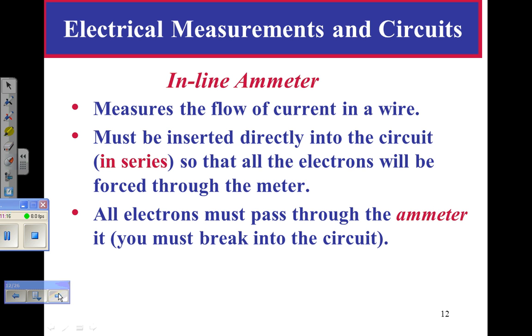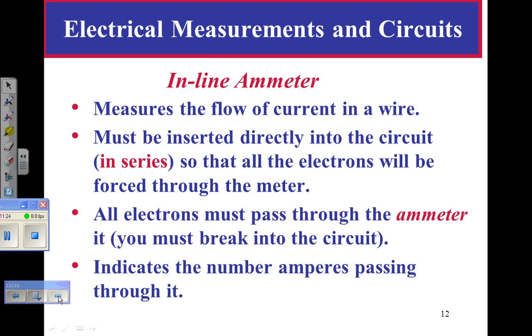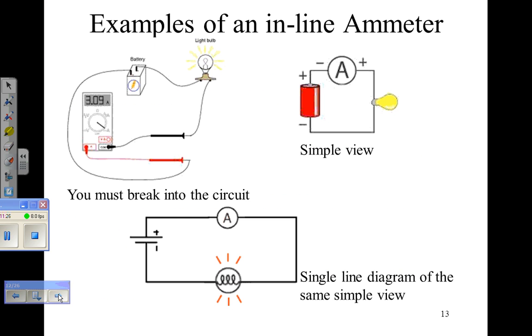So if you're going to read current with an inline ammeter, you must break into the circuit to read the current. And it indicates how many amperes are passing through that meter.